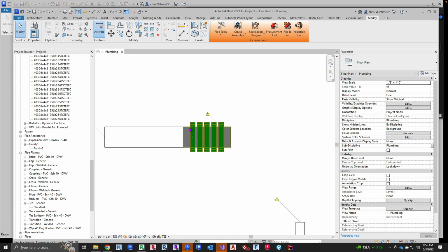I think so. One was just to double check. That last example where you had the nested family, it was the parent family that had the lookup tables, for the one that you wanted to manipulate? Yes. Well, the nested family also has a lookup table. We had to add that lookup table to the nested family.